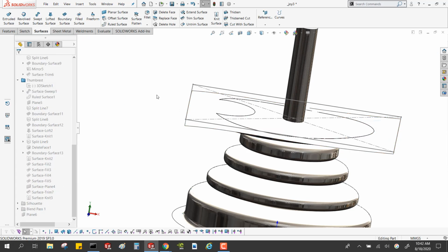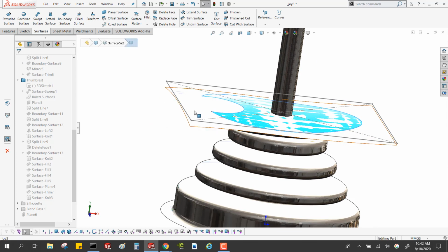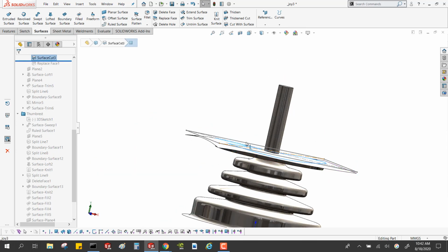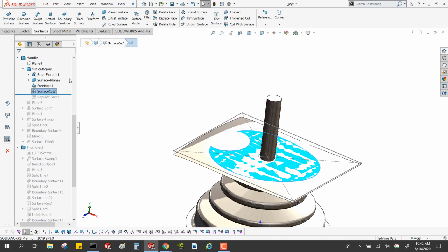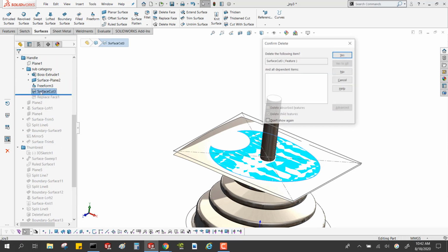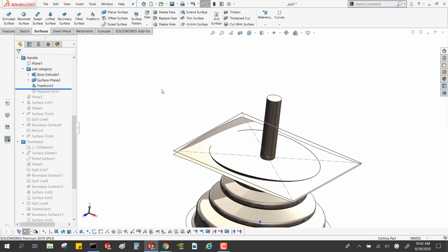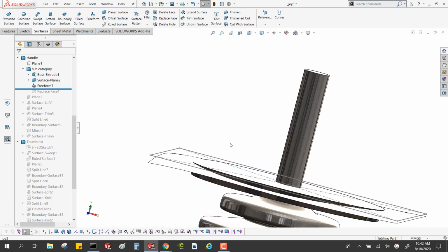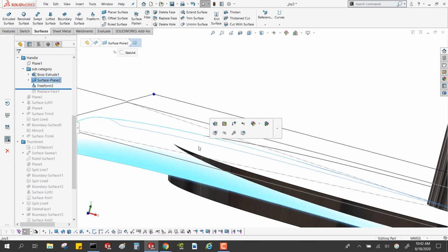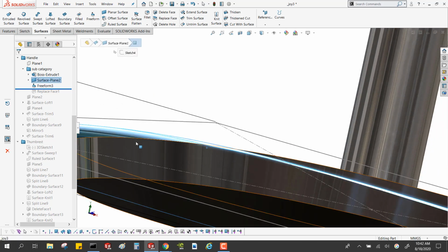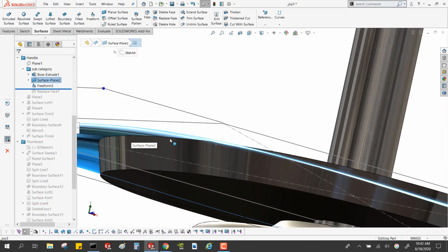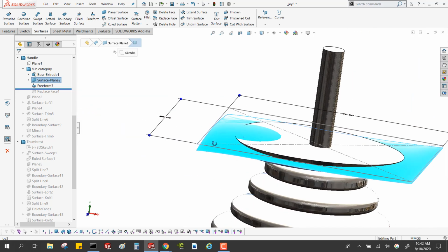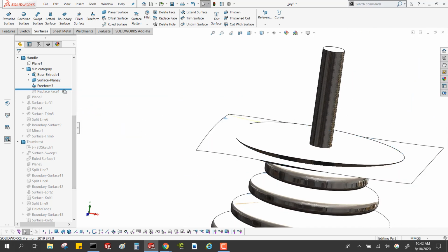The problem with this one is I had surface on top and bottom, so now I've got this gap here. A surface cut is good if it's only going in one direction, right? You're just saying, okay, from the top, cut that way. But the problem I've got here is this thing is actually going over the top of the face, so this isn't going to cut anything. I would have either needed to make the extrusion bigger, or there's another choice I can do.